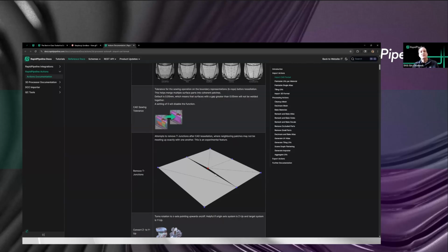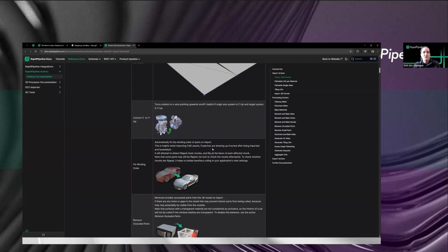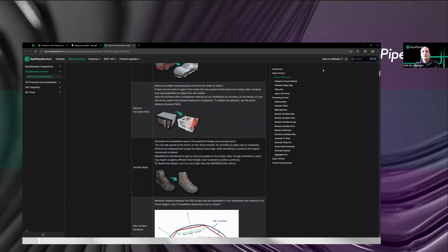As you decimate the surface down, if those gaps become visible, then you get these kind of hairline, busy holes in your model. And this feature will basically try to remove those by either merging this vertex together or creating a new vertex on the other surface and merging those. And so that's how that works. That's what T-junctions are all about. And then we can talk about some of the other functions.